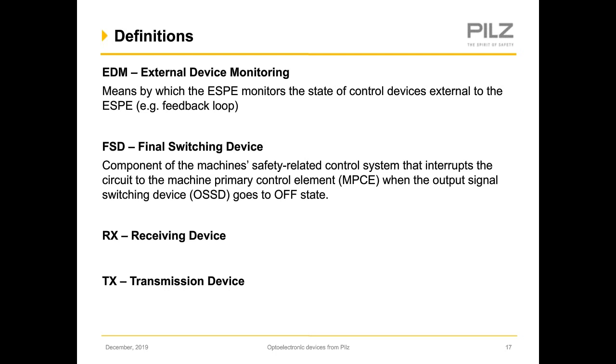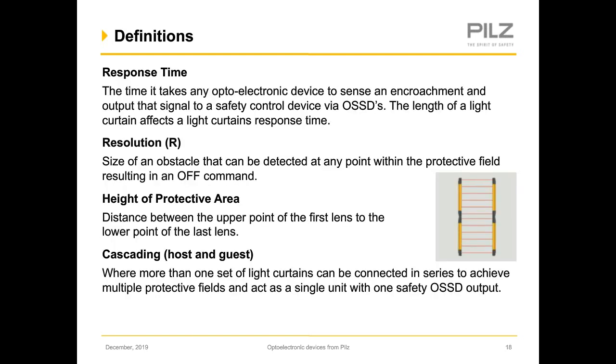We touch on response time because that's very important on these devices. It's the time it takes any optoelectronic device to sense an encroachment and output that signal to a safety control device via the OSSDs. The length of a light curtain affects the light curtain's response time.